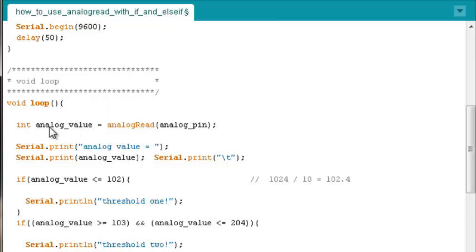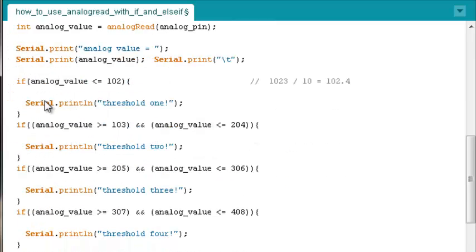collecting it into a variable, assigning whatever value is coming in off analogRead, and then test that variable for specific ranges stretched out from 0 to 1023. You know, if it's confusing to you, just think of it as 1023. It doesn't really matter, truthfully. That one off is not going to make any difference in this particular Arduino microcontroller. So that's a way to get 10 tests out of the 1023 range that you've got coming in.